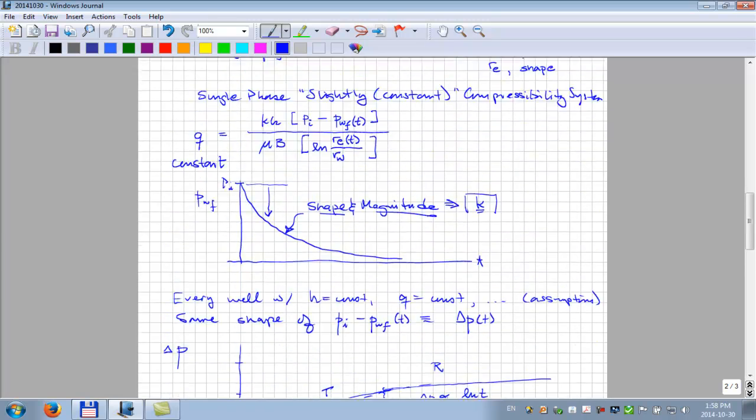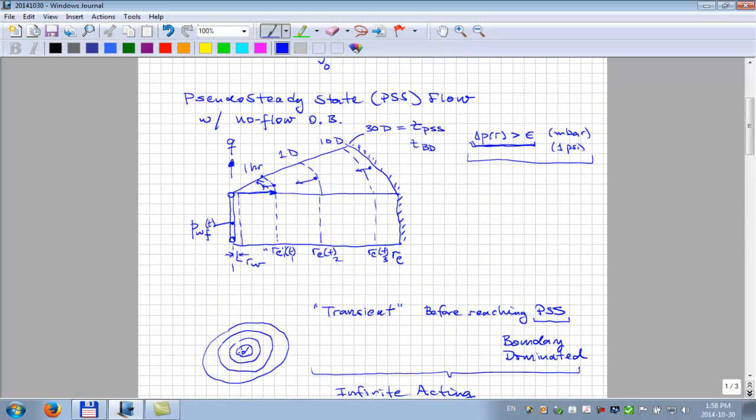So how can a radial well like this be linear flow? This is like cylindrical flow. Okay? Well, because if you look at the wellbore radius, if we blow up the wellbore radius there, RW, and you look at the time where we're only draining from just a little bit away from the wellbore radius, in other words, our local RE over RW is just slightly greater than 1, then it's linear flow.